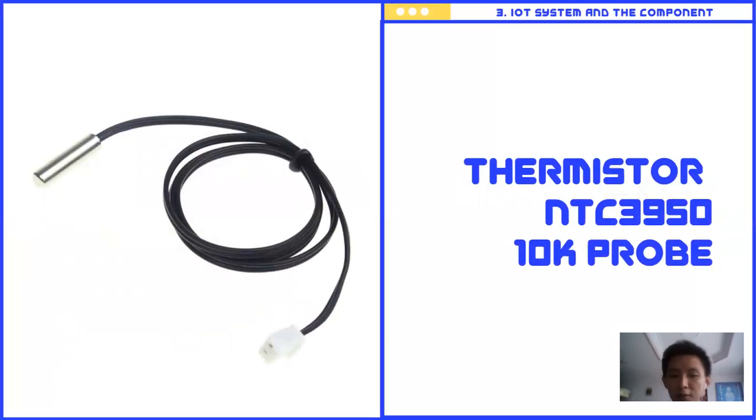And this is an example of an analog sensor, which is called a thermistor NTC 3950. It is a 10K probe. Actually, this thermistor is also used to measure the temperature of the engine, and this device is more effective compared to the potentiometer from the previous one, because at first we used a potentiometer, but after that we implemented this thermistor.